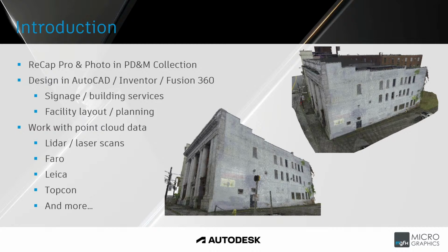Having a look specifically on this page at Recap Pro, it allows you to take point cloud data that comes from either LiDAR or laser scans, like the Faro, Leica, Topcon, many other brands out there, where you'd use a laser scanner to scan either the exterior or interior of a building, and then use that to design whatever machinery, signage, or services you may be required to design to fit in, around, or on that specific building. The laser scan would allow you to work with as-built data for your designs. So if you're in that sort of industry, then this webinar is definitely something for you to have a look at.